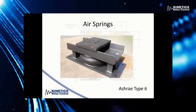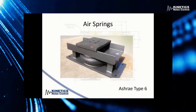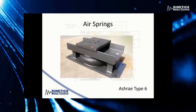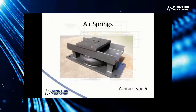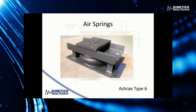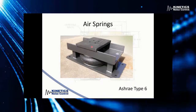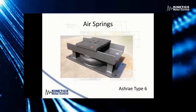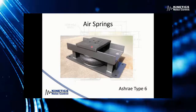Now, where airbags are really well utilized are in a situation where seasonally you may have a different weight on the equipment. For instance, if you've got a multi-cell cooling tower where the intent is to drain certain cells of the cooling tower in the wintertime, of course, the center of gravity of that piece of equipment is going to change substantially once you drain one of those cells. So now with the airbag system, it would level itself using the software on board.